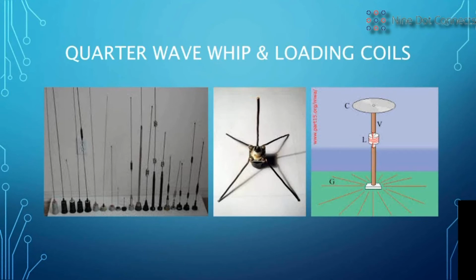They need to be at least a quarter wavelength long. At the very top, you can put a large piece of metal, like aluminum or something, and that's called a capacitive hat. It means that some of the current can flow in and out there and charge it up without the voltage going to extremely high levels. That's very important for making an antenna shorter and also preventing it from arcing over if you're trying to transmit with large amounts of energy. It reduces the voltage a lot.